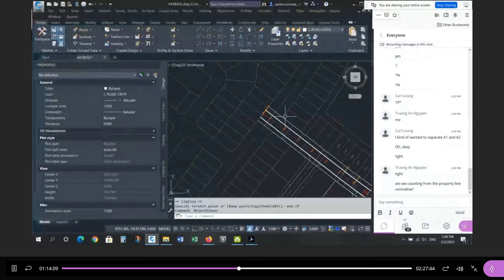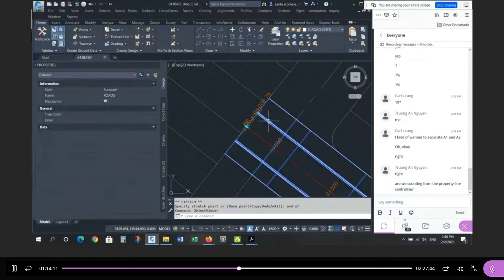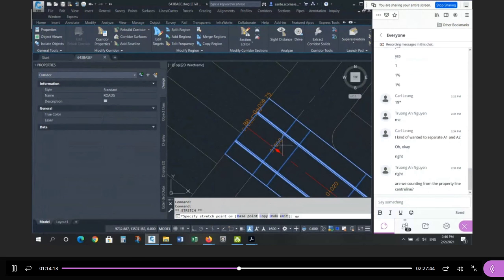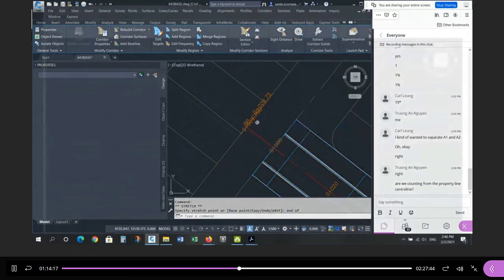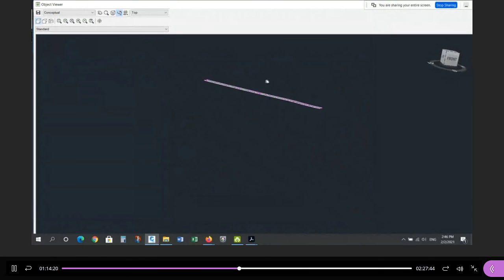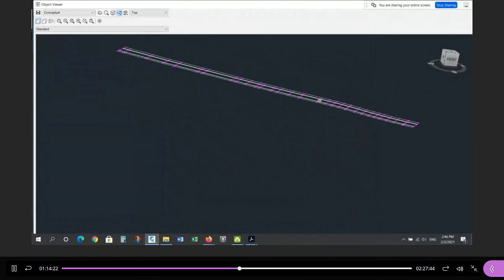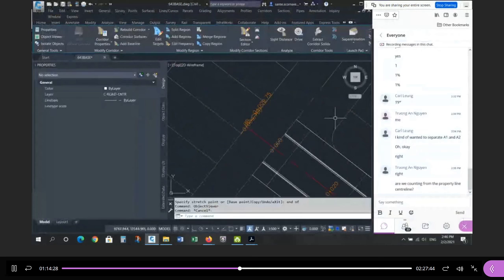At the beginning, it's the center line of the road. We started designing at 0. So I'm going to snap to the end point here. And now I've gotten rid of the spikes. There's my design. And if you look carefully, you can almost see the high point here and the low point here. High point here, low point here.